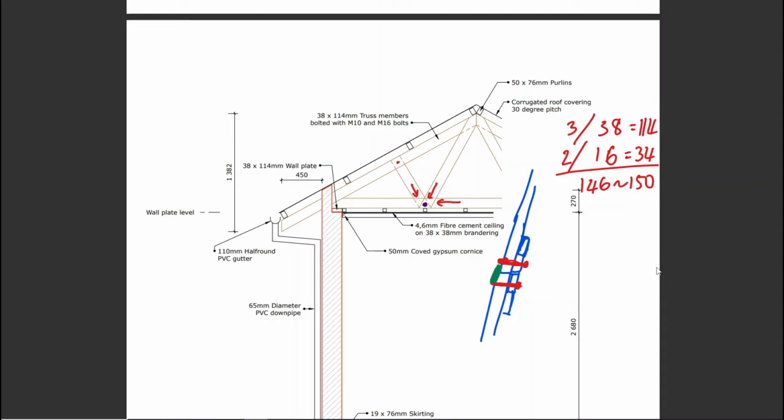But I thought, you know, this situation here is interesting. It is pretty interesting because you usually nail plate one component that meets one component, right? That's what we've seen typically is this piece, if it ends short, you're going to nail plate it across. You can agree with that, but it's very interesting to see now that we have 2 pieces bolted and they meet flush. You're going to have to nail plate it somehow.